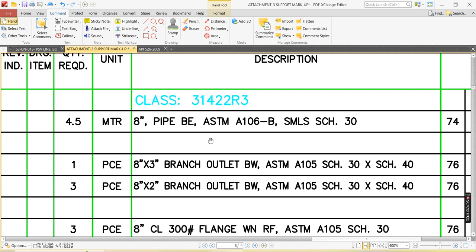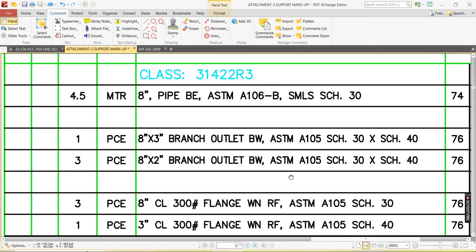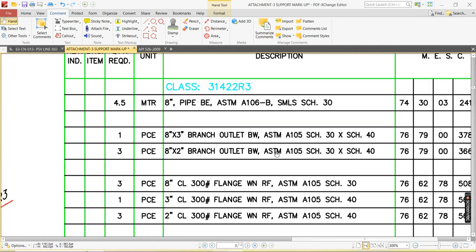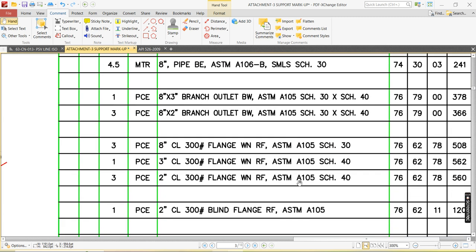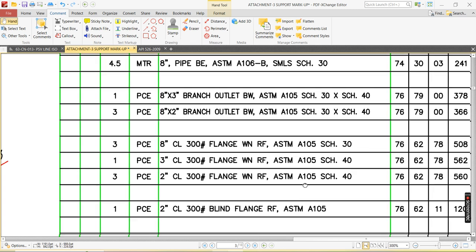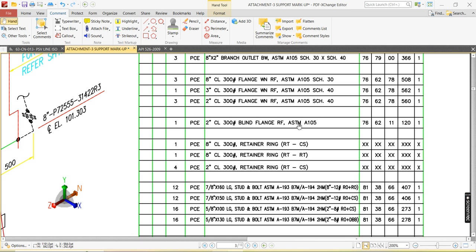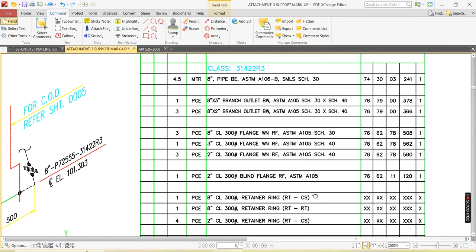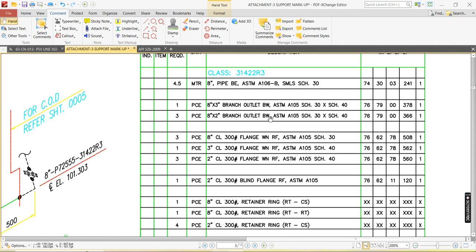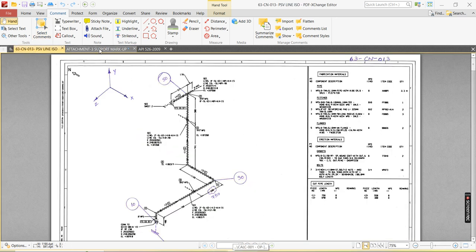We are not going to use any flange or fitting material, because the fitting material is A105, those are all forged material. Flange material is A105. So all will have different material, and we are not going to change anything. We will use pipe material only, because we are doing piping flexibility analysis only. Based on the pipe material and temperature, your expansion and contraction will occur. So please concentrate only on the pipe material. You have to change only the pipe material.